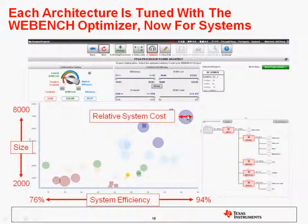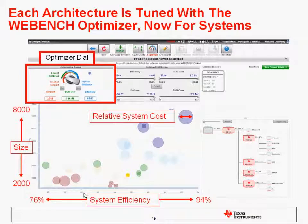The colors here are the different design optimizations. And so the blue over here on the right is the high efficiency. And so then we go from the knob setting of 5, the light blue is 4, green is 3, and so on and so forth till we get to the small footprint stuff down here in the lower left. And you can see this fundamental trade-off where if you want to have high efficiency, it's very difficult to get small size, and vice versa. If you want small size, the efficiency usually suffers. And that's accomplished through the optimizer dial in the upper left.